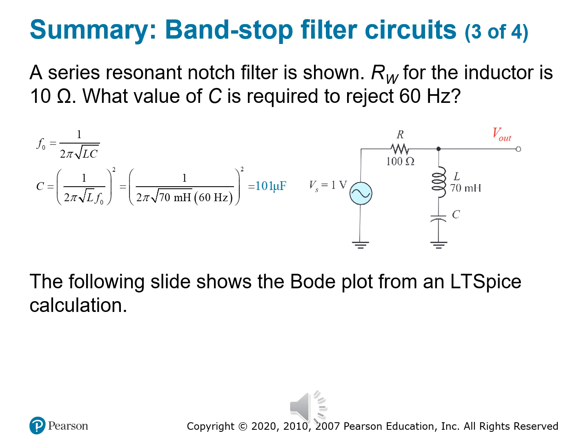So if we're solving for C, we plug in the numbers that we get, the resistor and the inductive value, and the frequency of 60 hertz that we're working with. We come up with a capacitive value of 101 microfarads. And that's it. That's the answer.